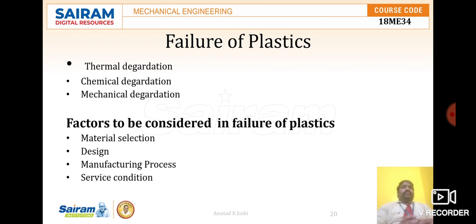Okay, even for the weight reduction or elimination of fabrication and assembly steps, or providing the right wall or rib thickness, or even the draft angles, etc., during plastic molding, the cost and finish of the product are a few important factors, and poor design is the leading cause of plastic product failure. So we have to design in such a way that it is an appropriate design, then we can expect a longer life of this product.